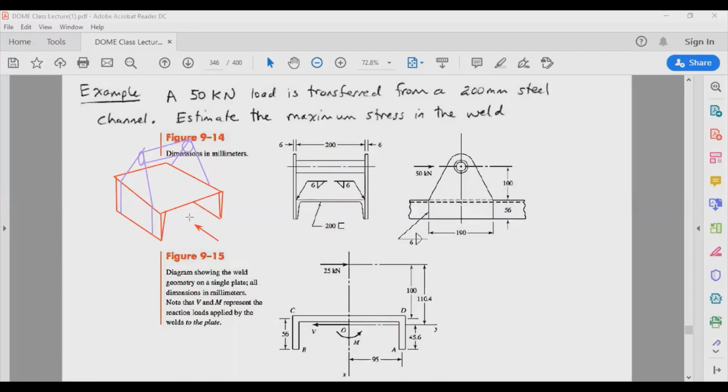Okay, so this is what we have, and I'm going to draw the welding in black. So we have the welding throughout. From here we have a weld throughout. This one is mirroring this end, and this one is mirroring this end. So you have a weld whose leg is 6 millimeters, and this one right there is actually here.